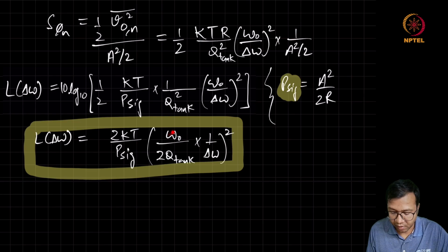And if you look at the oscillation frequency, then we can see that the higher the oscillation frequency, the higher the phase noise, because for the same amount of shift in the zero crossing at a higher frequency, it corresponds to a higher phase change. So this is the result of an LC oscillator phase noise due to a flat thermal noise.